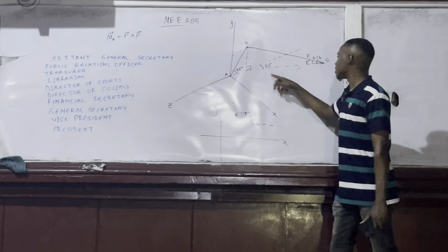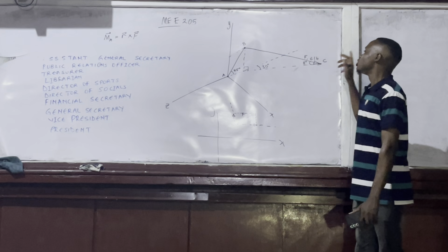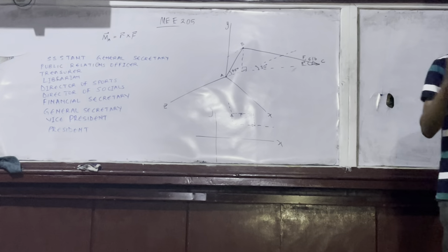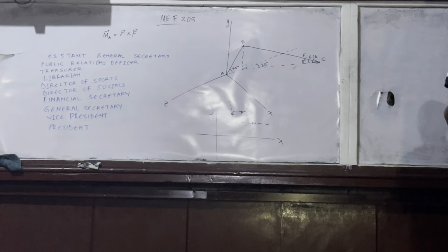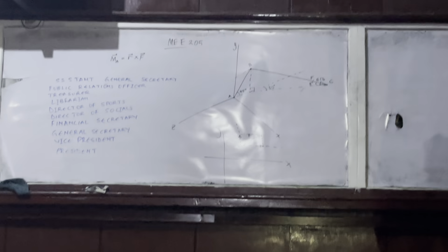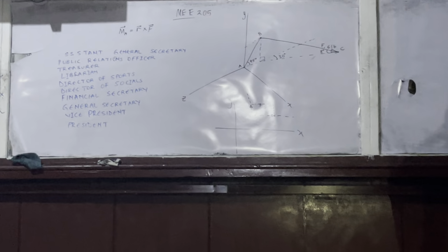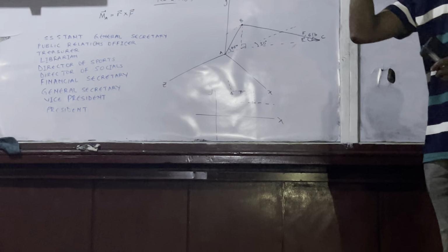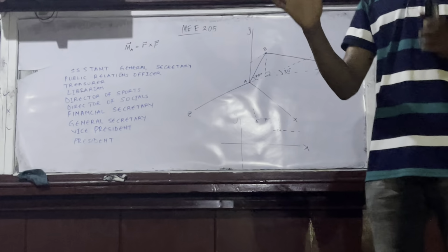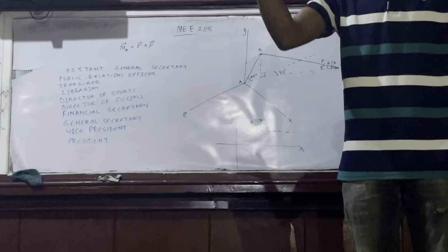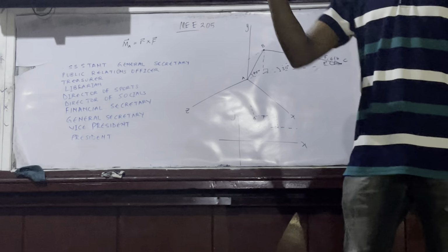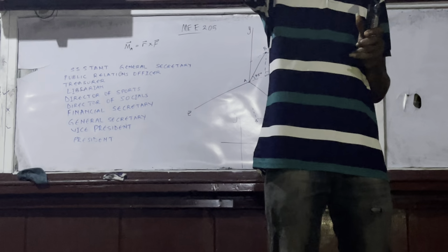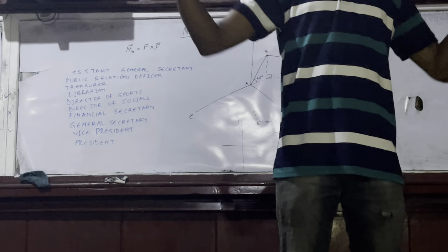Yeah. That axis, this axis lies in the xz plane. So the first thing we identified here is the y component of the force. The reason for this resolution is the fact that every force can only be resolved into two components. Any force that you can imagine, you can only resolve it into two perpendicular components. And those two components will be in the same plane with the force. So the first thing is we have identified the plane of the force. Once we have the plane of the force, then the components will be in the plane of the force.